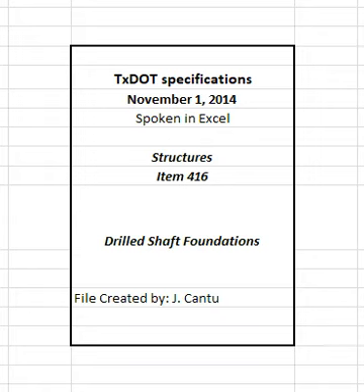4.1.2 Abutment bents and retaining walls. Shafts will be measured from the bottom of footing or cap elevation. 4.1.3 Other non-bridge structures. Shafts, including trial shafts, will be measured from the top of the shaft. 4.2 Core hole. Core holes will be measured by each core hole drilled.